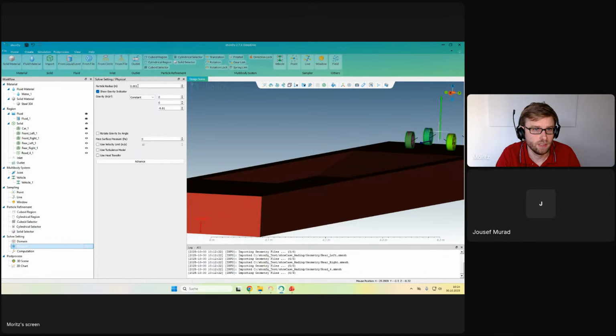And also the size of your particles. You can compare the particles to your mesh size in traditional CFD. So if you use it, I would already recommend that you also do a refinement study on the particle size. As in traditional CFD, where you do a mesh study, you should also do a particle radius study. Okay, this is the setup.